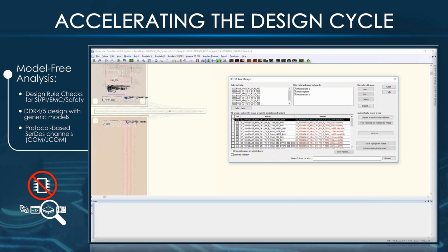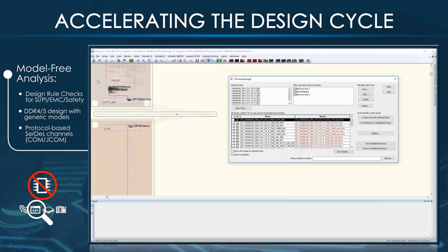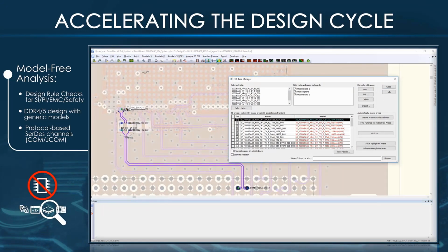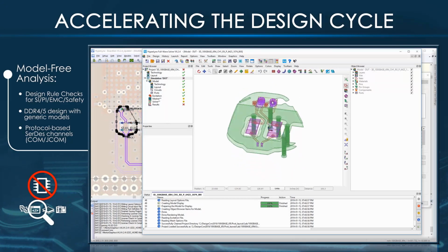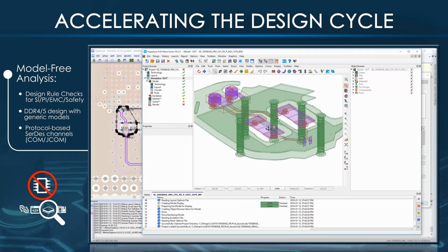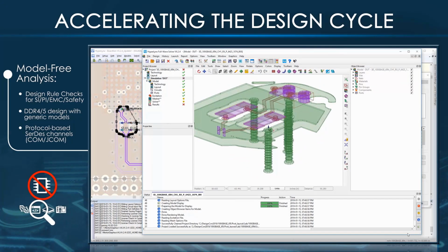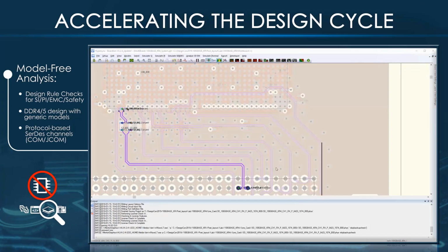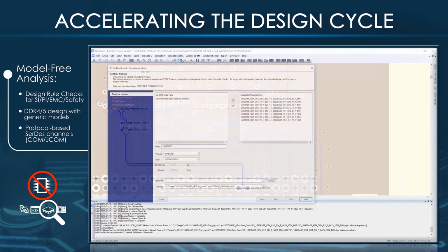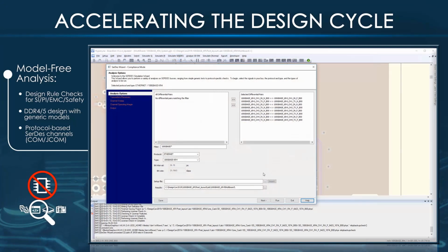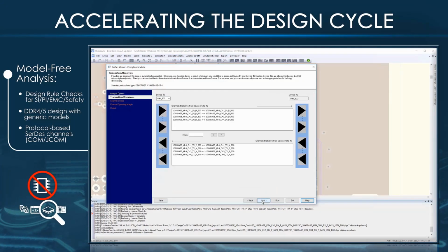And then it also automatically finds any areas needed for 3D analysis. Again, this is a very powerful feature. It basically finds any of those irregular structures like vias or these DC blocking caps and automatically generates a 3D model that will get sent off to the 3D solver and solved, which then gets used in the analysis.